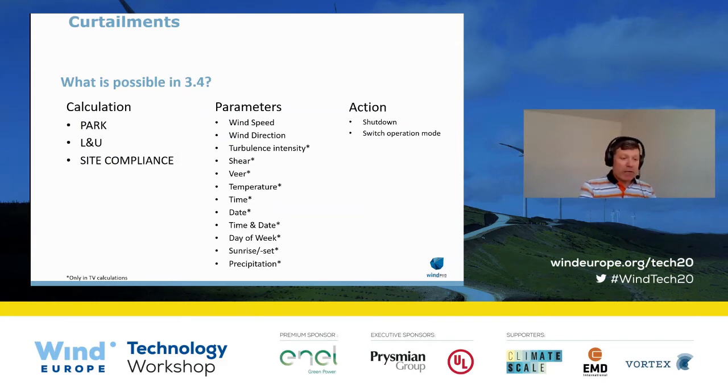Quickly speaking, if your turbine is shut down for whatever reason and for whatever curtailment necessity, obviously the turbines behind will not be affected by wake added turbulence. That, of course, has an impact in this kind of calculation. Thus, you can avoid redundancies and erroneous calculations, taking these curtailments into account, and thus having a correct result out of it.